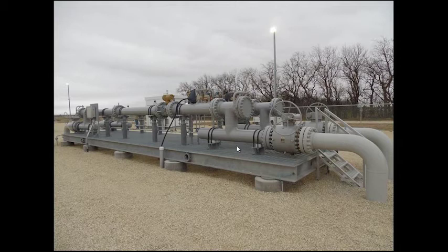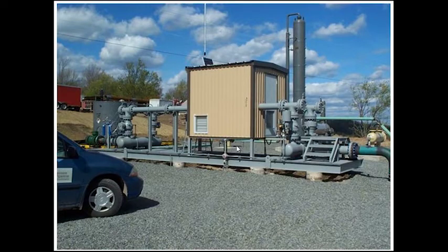What I would propose would be a better design, though, is to shorten the skid and end it right here. Drop down off of the T's all the way down directly into the headers. Take your block valve, put it in the vertical position here. You've got a lot of opportunity to fit that valve in that arrangement. And in so doing, you lengthen your riser lengths. You have a lot of opportunity to recover velocity profile on entry to the meter tube, and that's a better situation.